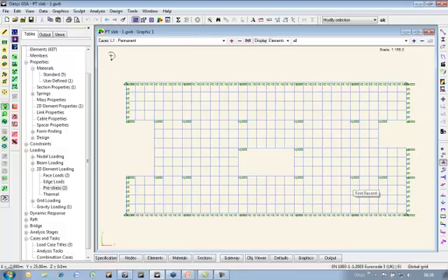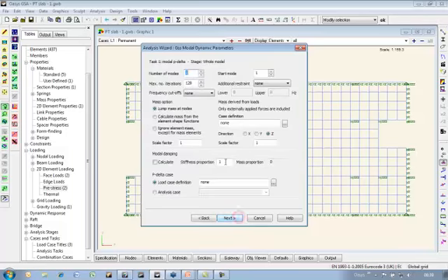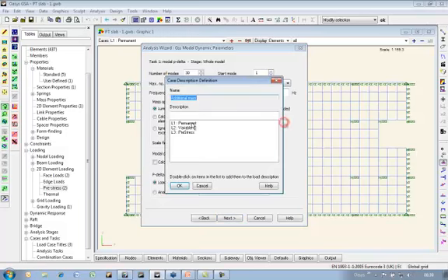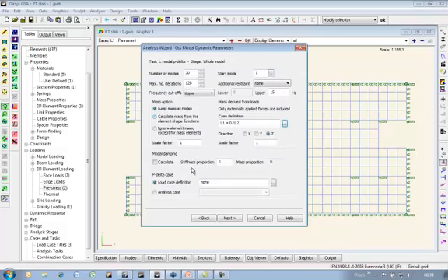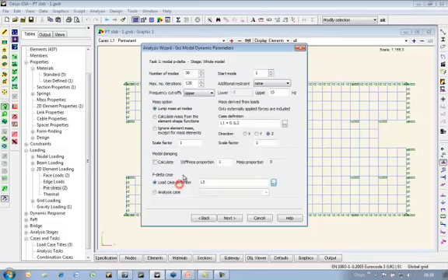And we can account for this by, rather than just a modal analysis, using a modal P delta. What this does, again, if I just take my 30 modes with an upper frequency of 15, and again my variable and permanent loads, but we also have the P delta load, which is the pre-stress load on the slab, and this loads up the structure and affects the stiffness accordingly.